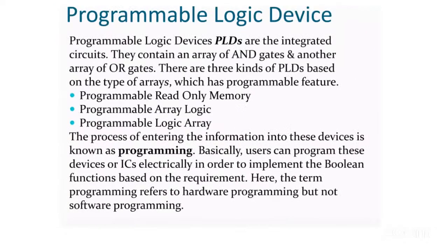The programmable logic devices, PLDs, are integrated circuits. They contain an array of AND gates and another array of OR gates. There are three kinds of PLDs based on the type of arrays which have programmable features: programmable read-only memory, programmable array logic, and programmable logic array.